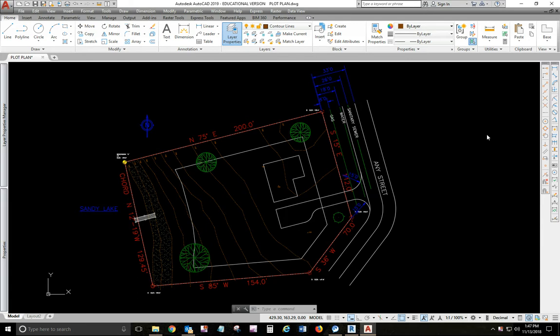All right, so weeks 13 and 14, you're going to be working on a site plan or a plot plan. And there's three different ways of doing it in Revit. The CAD learning videos showed two different ways. One, you bring in a points file, which is survey data, and then Revit builds the contours and the topo surface from that. The other is to bring in a 3D drawing of survey data, which would be created in a program like Civil 3D, and you can bring the surface already in and then create it from that.